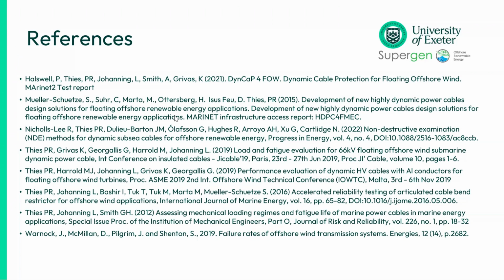Yeah, I think that's the answer there. Thank you, Philip. It depends on context. But I believe having those interface tests is important, and that's why I showed those two, because you can qualify the bend stiffener on its own, but what you need in that service simulation realm is to have it attached to the cable with some realistic loads. Yeah, totally agree with you at this point.